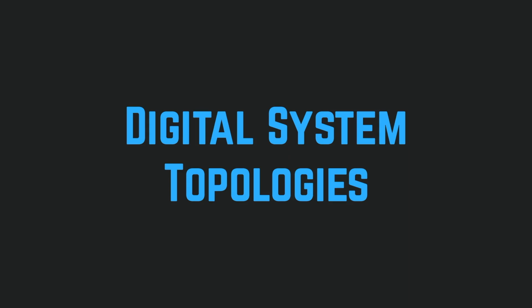Since we now know that we can abstract two voltages of the system with ones and zeros, I'm going to use ones and zeros to discuss functionality, but feel free to use a specific system like logic 1 equals 1.8 volts and logic 0 equals 0 volts to connect the discussion of zeros and ones to specific voltage values.